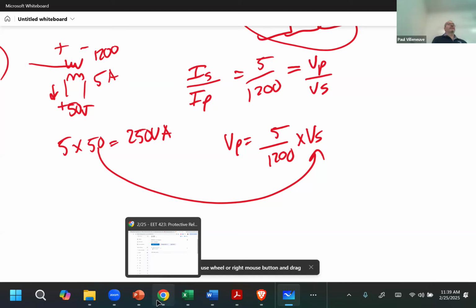But the transformer has to be putting out more than 5 amps for a 1 ohm load at 50 volts. Not, it's a current transformer. Yeah, you're talking about two entirely different elements. Where's the other current? There's losses in the transformer, right? That's all transformers too. It's stepping the current down, which means, right, that the voltage has to go up. So that's why it's 50 volts on the low side, and it's gonna be lower. It's 208 milliamps, yeah.